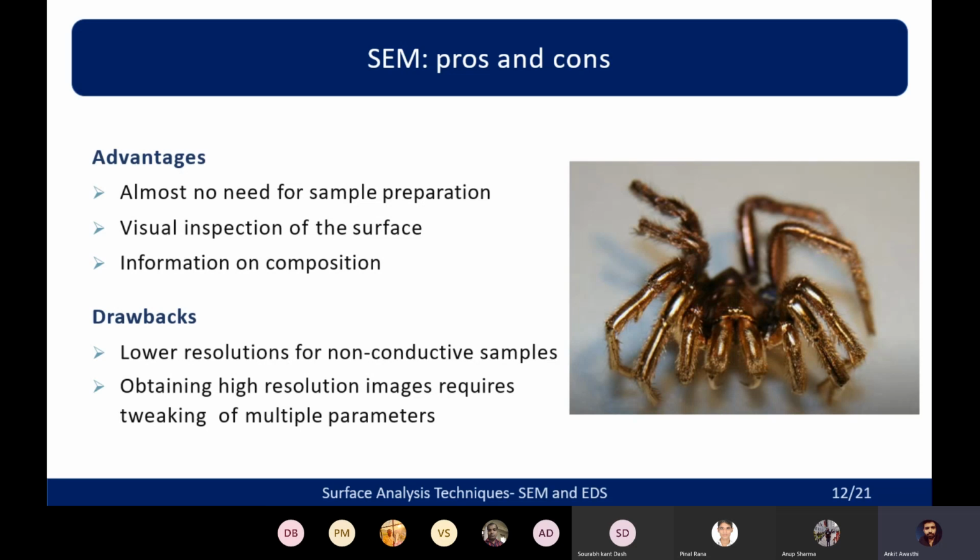So if you say, I want to analyze the laser scanning path or something, they try to get that, and their main focus is to get that, and then they set the parameters according to that so that we get our parameters according to our requirement. And here we also get some information about the composition using this BSC mode, the backscatter electron mode.